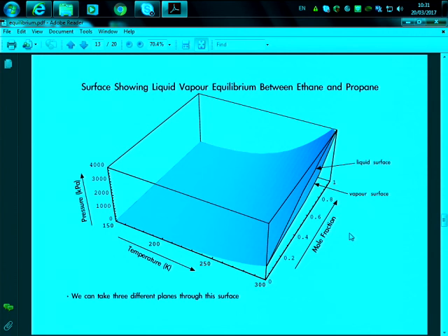Regarding this graph, this is only for methanol, yeah? So if you were having 73 and having the vapor, then at 73 you will get this amount of vapor, right? And then as you increase, the percentage of methanol will decrease and the percentage of water will increase, okay? And then when you reach 100, basically you won't have any methanol anymore because most of the methanol will have gone, and you basically have water, and that's why you're able to reach 100. Otherwise you're not able to reach 100 because you have a binary mixture. So here you have a pure component. So basically if you have a solution of methanol and water and you reach 100, you don't have methanol anymore in the system. Yeah, is that all right?